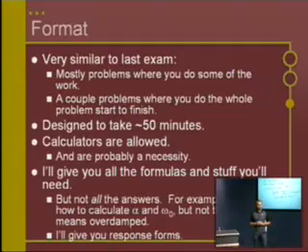So all you have to do is take a look at what the circuit looks like when the switch has done its change, zero out the sources, and find out what that is. You're not actually doing the full-blown first-order analysis. You're just finding the time constant. Or I might ask, if these are the values of a parallel RLC circuit, is it overdamped, underdamped, critically damped? What is going on with the circuit there?